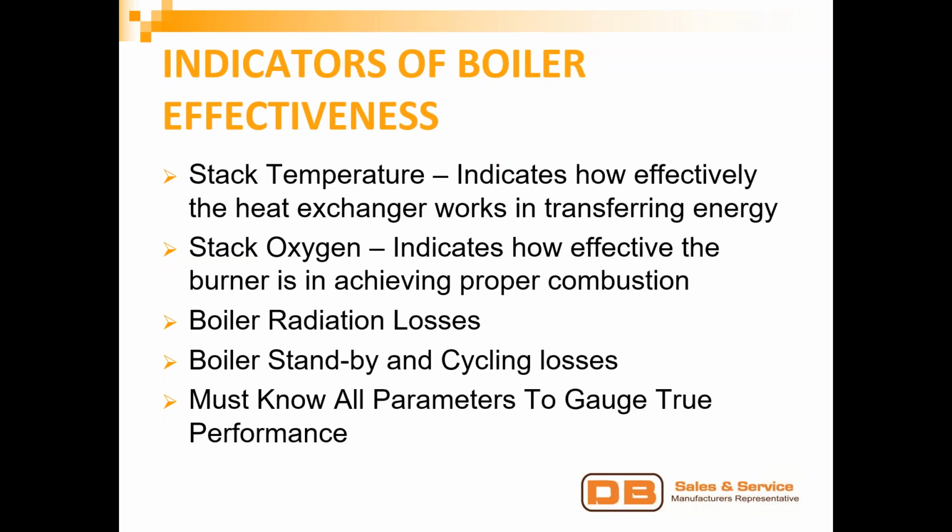So stack temperature is a great thing to monitor if you're looking to monitor boiler efficiency and how well that heat exchanger is working. As your heat exchanger gets dirty over time, the stack temperature could creep up, or it could be becoming less efficient over time as well if the heat exchanger gets damaged or anything else.